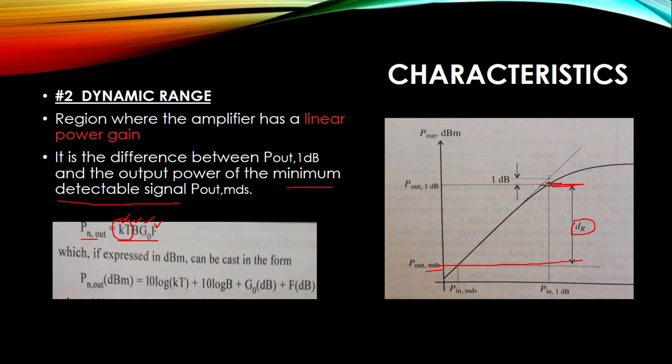So repeating the parameters, KT specifies the temperature variation, B specifies the bandwidth, which is the acceptable range for the amplifier, G0 specifies the gain of the RF power amplifier, and F specifies the noise figure that is contributed due to the amplifier itself.